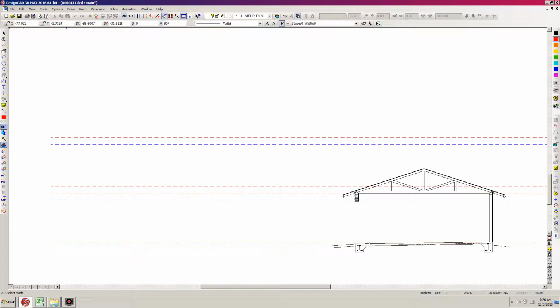So at this point, I'm going to assume the landing will end up being... let me see what this is at the front of the garage here. Hit B for vector, right click here, and then go over here and gravity move. It looks like I'm 4 inches on the Y distance, 4 inches below the finished floor line at the front of the garage. So that means if we go 1 foot below the finished floor line, the top of the landing would be 8 inches below this front end of the garage, and that seems appropriate to me.